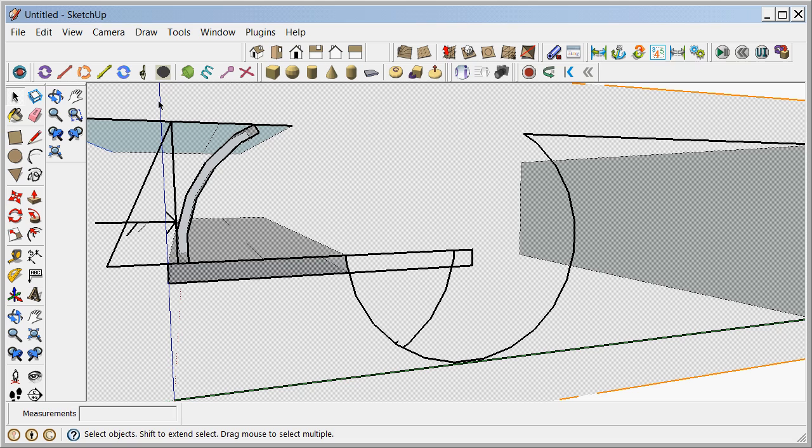You've got nothing on top here because it is a free surface, but if it was down deeper underwater, you would actually have a pressure surface that would be a rectangle, and you could draw its resultant someplace there, right, acting down. If you knew how to draw. Okay, you got a resultant there.